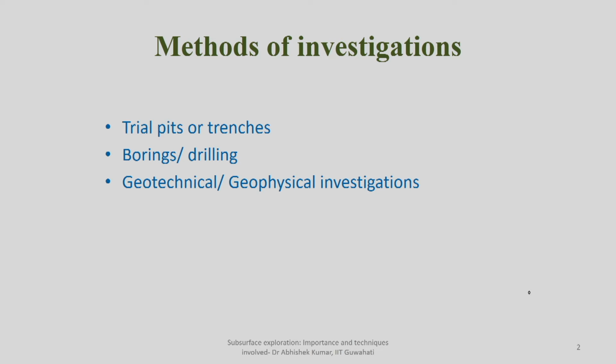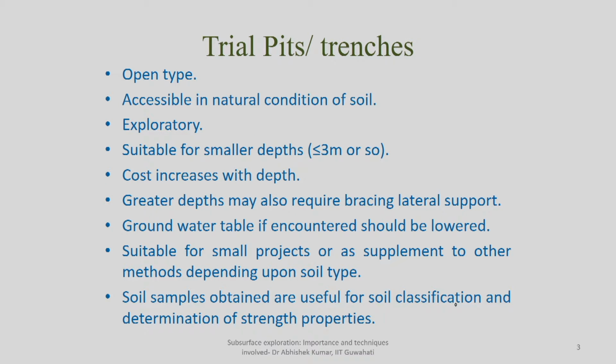In today's class we will focus more on trial pits, trenches, and boring and drilling methods. As we mentioned earlier, trial pits are basically open trenches or open pits which you dig at the site of interest. You find a reference distance from a nearby permanent structure, which can be a building, a tree or an electric pole, with reference to which you can locate the site where you are going to dig and collect the soil.